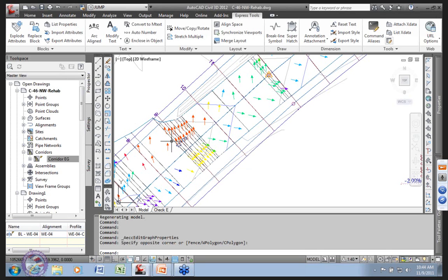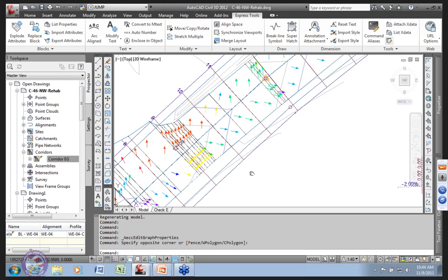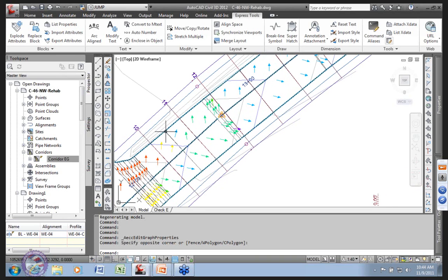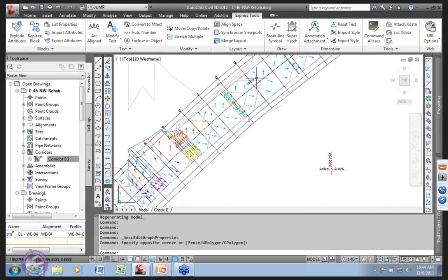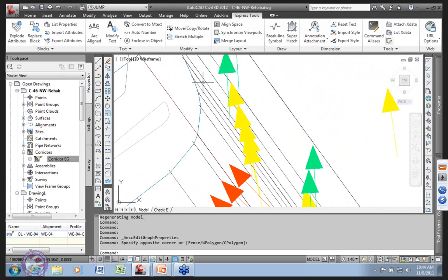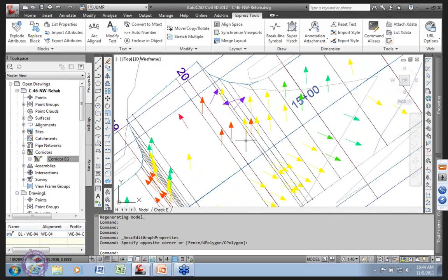And you can see that because we're using an overlay and using those edge targets, we start to get more sampling. And in fact, at any critical point, in other words, at any node that we picked to create our feature line, we will get that additional density of cross sections, applying our parameters into the corridor.